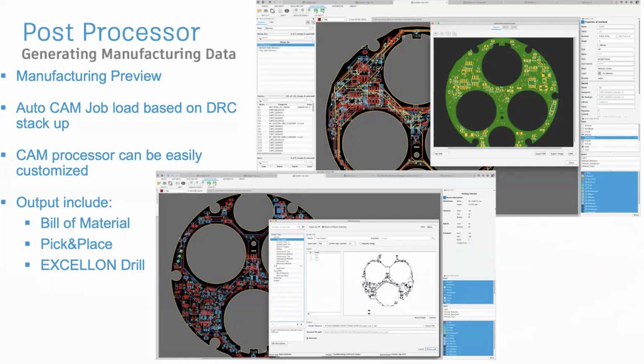be receiving in the mail if it's unpopulated, the board you're going to be getting back. You could take a view from the top as well as from the bottom. And if you go to the different available tabs within the previewer, you're going to get a lot more information about the details, such as how many components, how much copper, polygons. You're going to get a lot more manufacturing data out of that tab that may be necessary for the board house to get the boards made.